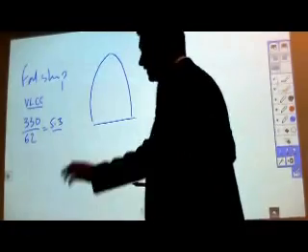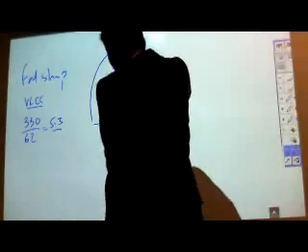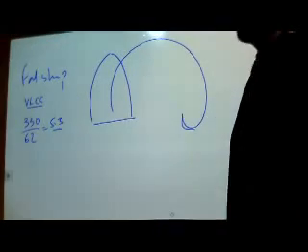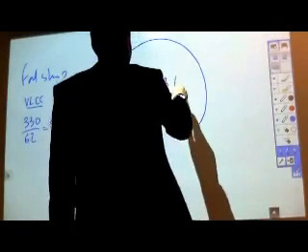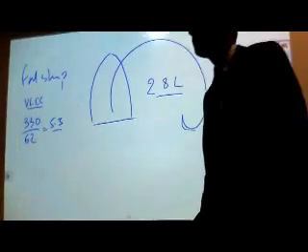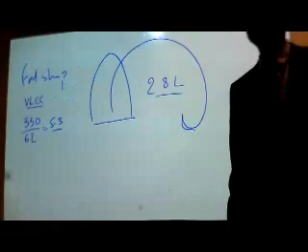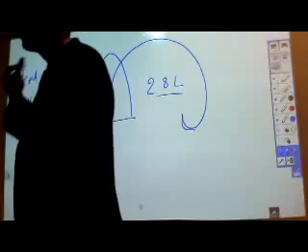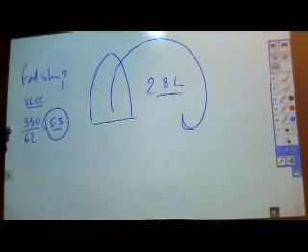But when a ship is not directionally stable, it will be very good at turning. The turning circles will be somewhere around 2.8 times the ship's length. It will have a sharper, tighter turn. It will turn well because of this length to breadth ratio.